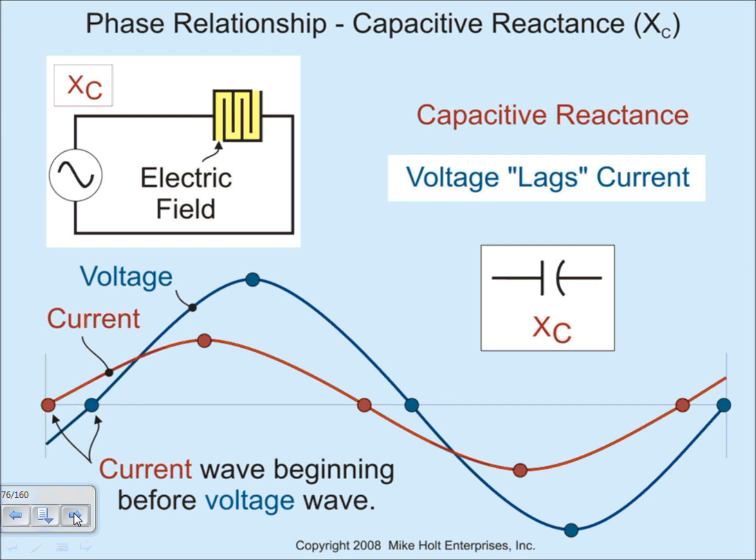Phase. This is what I want to emphasize, guys. For the capacitor, the impedance, as we said, is Z, and when you calculate it, it's 1 over 2 pi F C. That's how you calculate the impedance of the capacitor. Capacitors always make the current lead the voltage. Now, Jackson, my friend, some of you will ask, which one is better, leading or lagging?